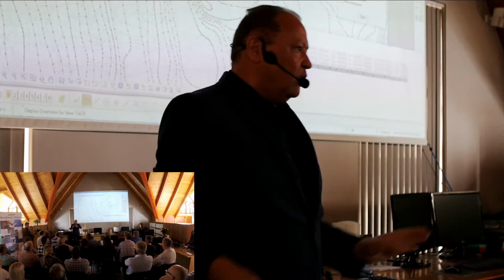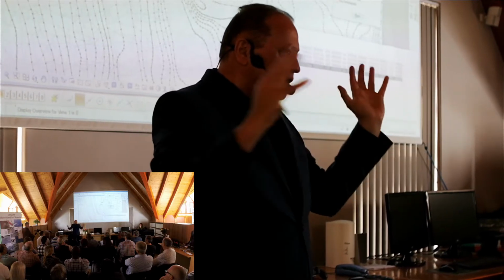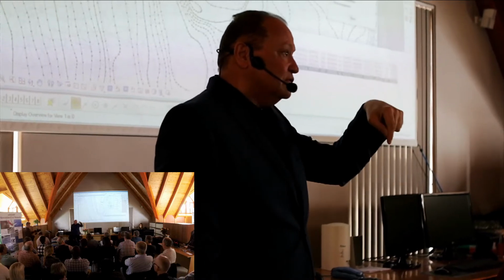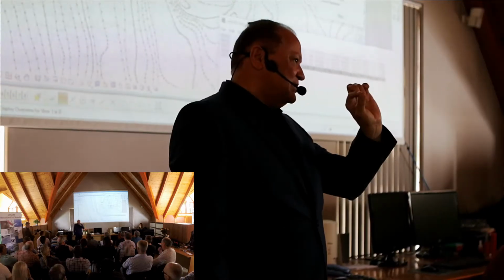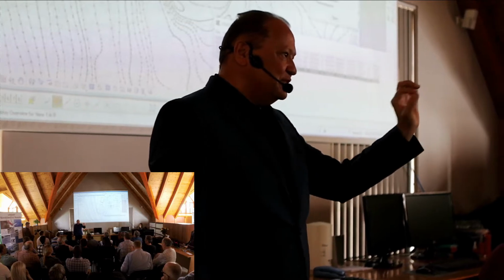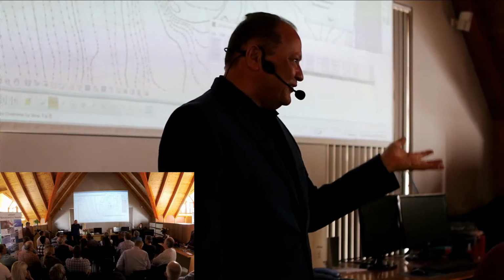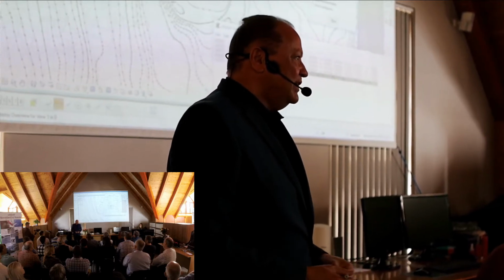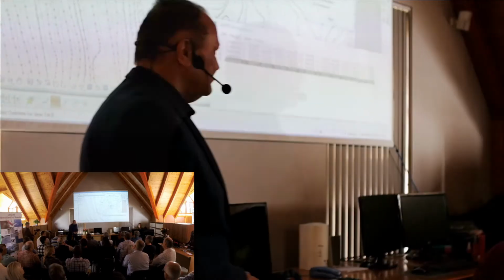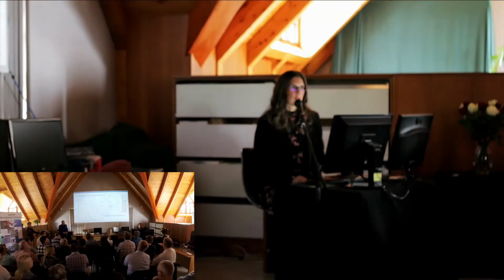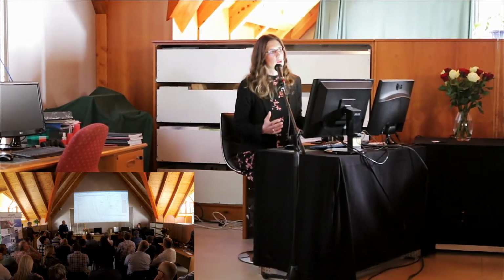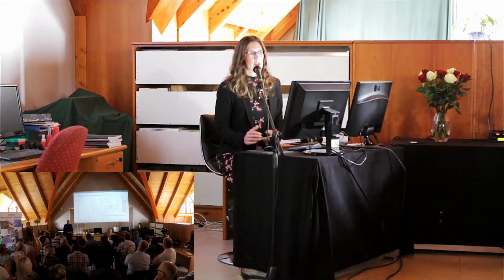And that's now a flat wall, but it can be a silo tank or whatever you want. So in uSMART, contours don't need to be points of equivalent height on the surface of the earth. If you look up the definition of contour, you can contour the wall, and you can contour at any perspective that you want to. I can make an isometric view, see my contours, and edit them, so I can visually see what's happening. And obviously with your S-line topology, you can also shade it, which helps a lot.